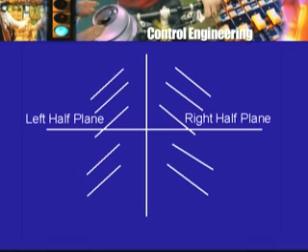This phenomenon of things happening because of poles in the right half plane or on the j omega axis is vaguely referred to as some kind of instability, and it is connected with the boundedness or the response going to 0 or staying constant or being a sustained oscillation or growing indefinitely. This is what is connected with the poles of the transfer function. So just by knowing what the transfer function of the system is, you are able to say something about at least one part of the response.